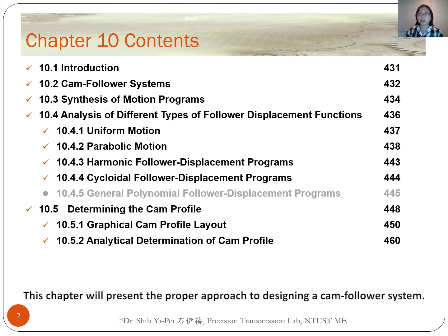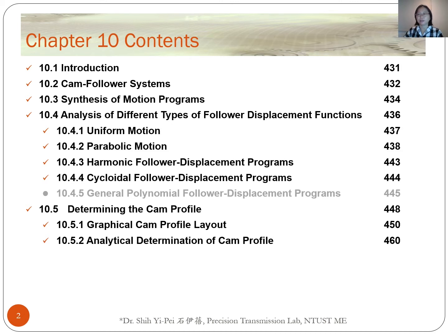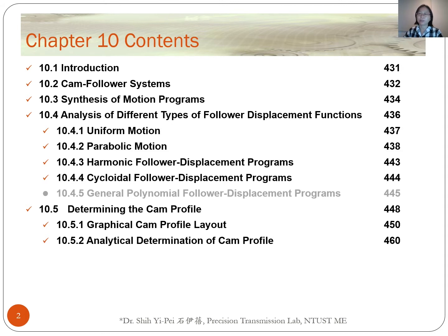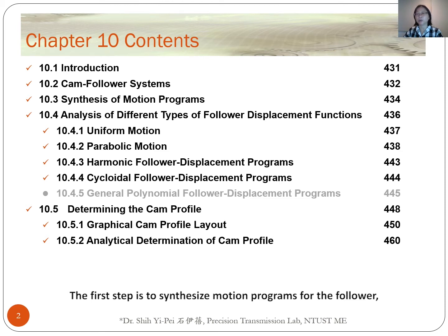This chapter will present the proper approach to designing a cam-follower system. I will introduce kinds of cam-follower systems and how to synthesize motion programs for the follower motion. Cam design usually requires two steps. The first step is to synthesize motion programs for the follower.